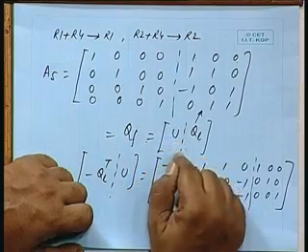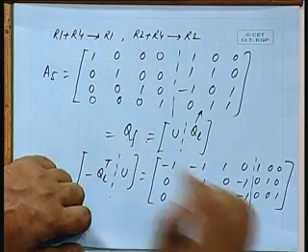Starting from the A matrix, we have got BF and QF by these elementary transformations. So, if you are given an A matrix, first of all through echelon transform you have to find out a possible tree. If you find out a possible tree, then again rearrange the columns, get A, so that you can partition A into AT and AL, and AT is a square matrix which has to be transformed to a unity matrix, and automatically the right hand part, that is the part associated with AL, will also get transformed, which will be generating QL. So, U partitioned QL, this will be the total matrix QL.